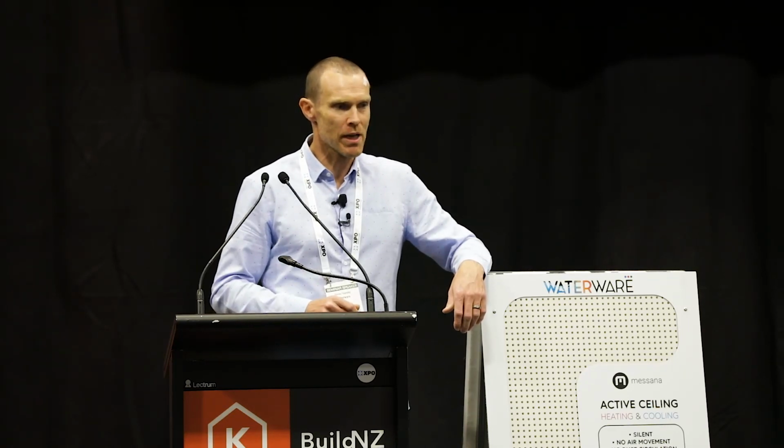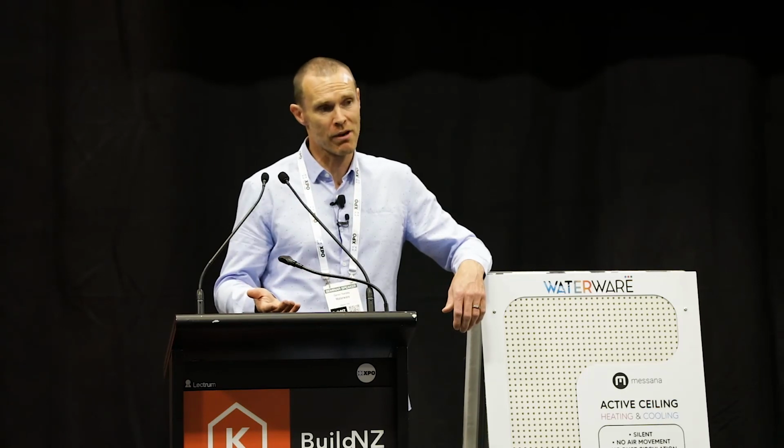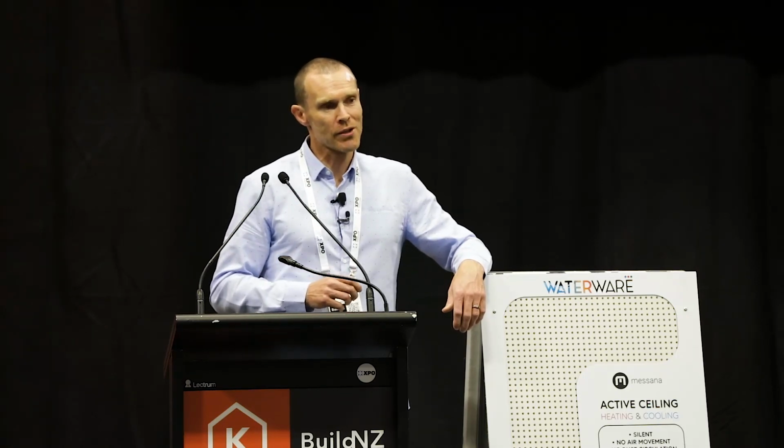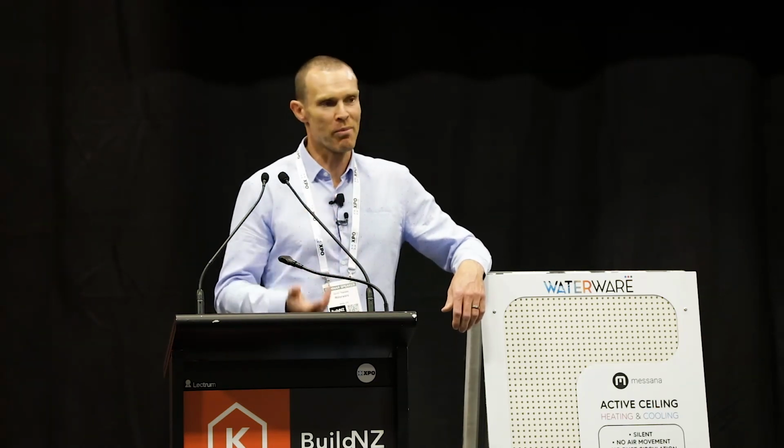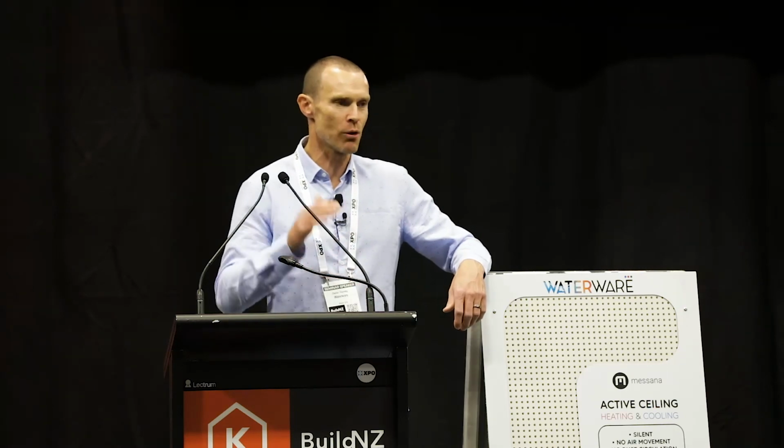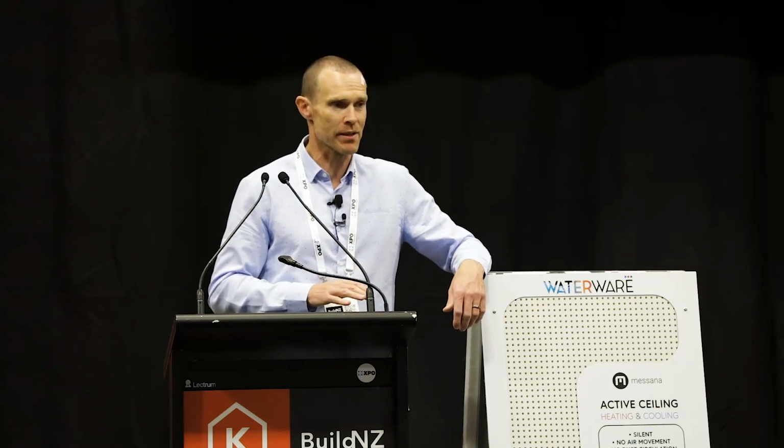So it is a significant investment, but it raises the level of performance from a 4-degree reduction in summer to an 8-degree reduction. And it also allows you complete flexibility with your floor coverings then. So if you want engineered wood or a high performance carpet, something like that, that all reduces the performance of your floor heating system, whereas typically there's nothing between you and the ceiling, so you've got complete flexibility.